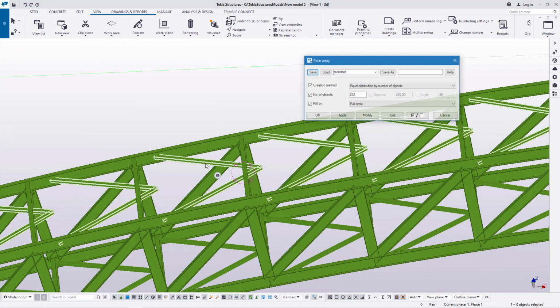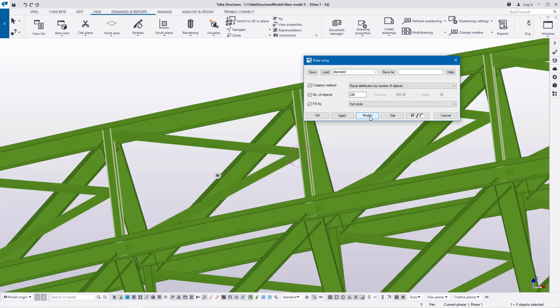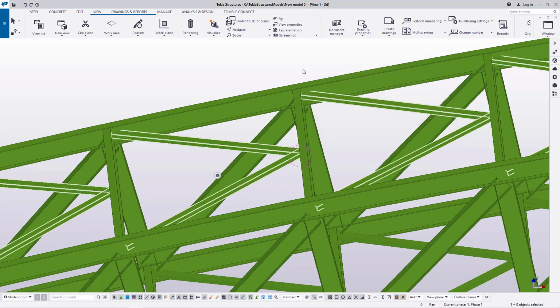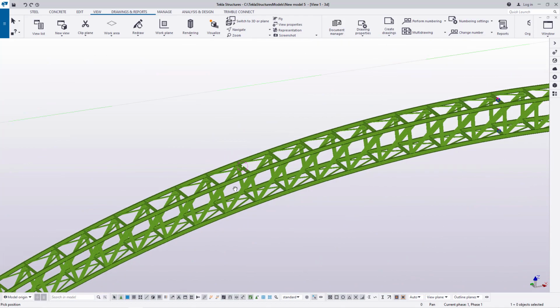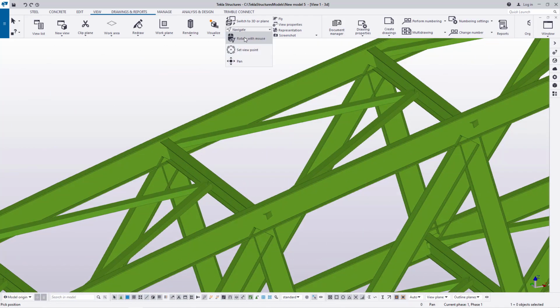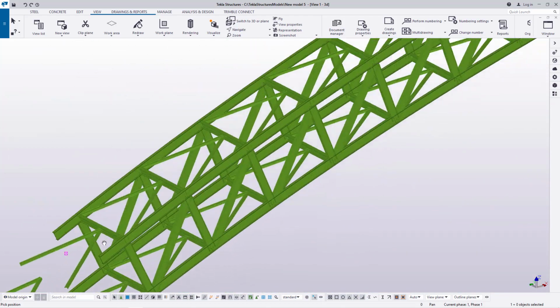What you can do is just double click on it, and we want to either increase or reduce the number of these braces so that they fit to the particular position that we intend them to create some support to our footbridge. Now I'll come here and feed 46. We need 46 of them, not 252. I'll click modify and see whether they will respond. I'll click apply and accept that, and if you walk around, you'll be able to see all of them have been repositioned perfectly well to their respective position where you intend them to be. So take a look. This is how it looks.